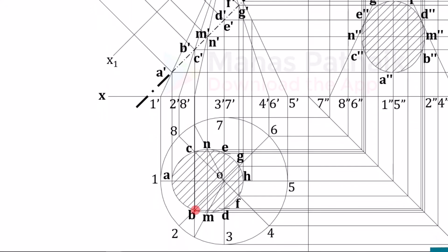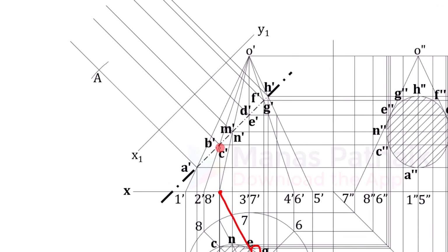Let's go for B. Sir, that's point B. So keep one leg of your compass on xy, other leg at B. Now this has got to be absolutely perpendicular, with that much as the radius. Now follow the path, and then with respect to x1 y1, cut an arc again, that is B. Okay, in the same fashion you can get point C also. This is going to be that arc, this much as the radius, and then with this as the center, cut an arc, that's point C.